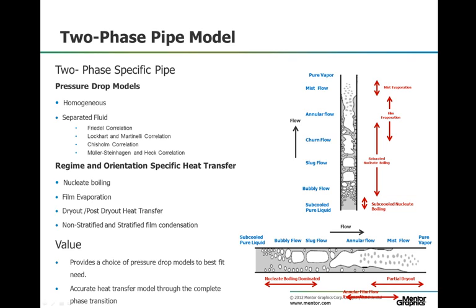When considering two-phase flow, heat transfer and flow regime modeling is the key to having a viable solution. Boiling, condensation, and flow regime identification are all dependent on temperature and the heat added or extracted from the fluid. This is further complicated by gravitational effects on the fluid and flow regimes. These complications are due to the fact that inertia, viscosity, and buoyancy effects can be attributed to both liquid phase and to the vapor phase, and also due to the impact of surface tension effects. Therefore, it is critical to understand not only energy inputs but also the orientation of the pipe when modeling the heat transfer effects of the two-phase pipe.